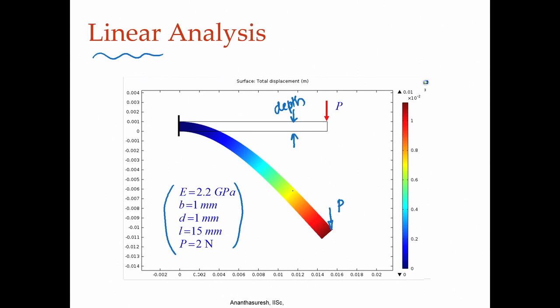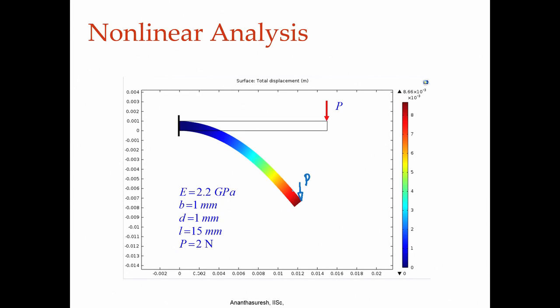When you compare the one we had before and now, with the same data, all that has been done is to check the box that says consider geometric nonlinearity, and then you get a realistic picture. So, nonlinear analysis, as we also said last time, gives you a realistic picture of what happens to the real compliant mechanism. Now, we can understand what we said with beams.